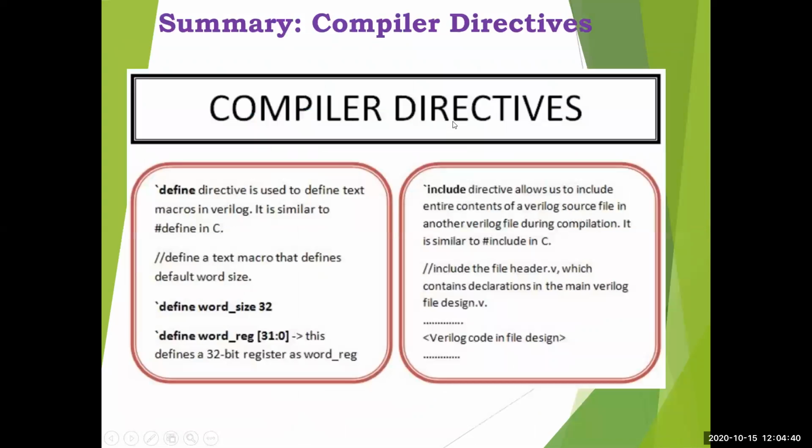And then finally we have seen the compiler directives. There are only two compiler directives in Verilog. Many, maybe two or four, are there, but these two are important, and we have discussed them here. The `define directive is used to define text macros in Verilog, which is similar to #define in the C language. So this is the example we have seen.